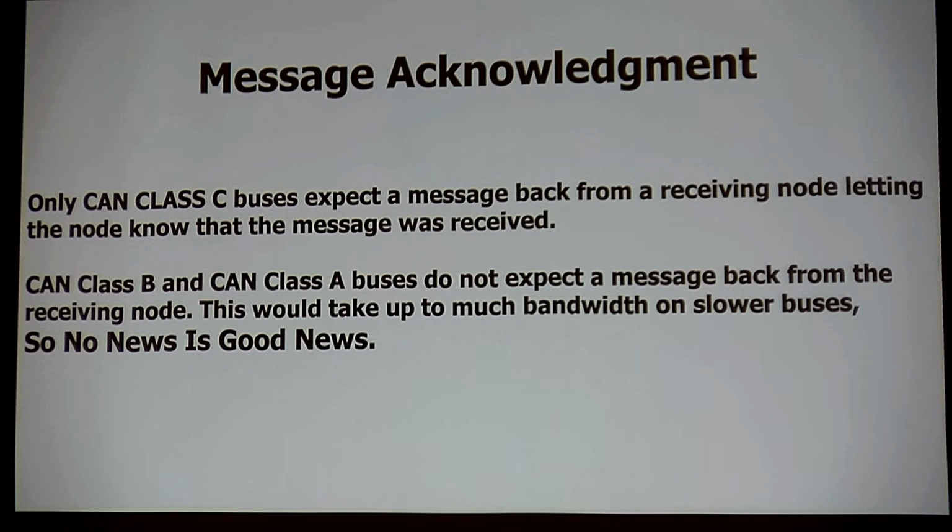So you're not trying to program a dash that's dead. We program this dash with factory Volvo software. It says it's successful. Is it successful? No. It said that the program was able to talk to the DIM, because that's what establishes who I'm programming with, right? Because you're going to tell everyone to get off the bus because now you're going to program it. And now we're going to start to set a string through the system where we're not arbitrating, but we're loading a program, right? We can't have a bunch of noise on there. Well, what does it mean it was successful?